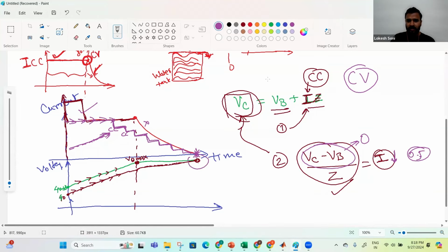Okay. So in that case, when you don't wait for zero and you stop charging, if I zoom this part, this final thing, this brown curve, which is of battery voltage, would sort of settle down like this. And this is that RC behavior which we discuss in our other webinars. So this is zoomed part. It would settle there only, more or less. Okay, so this is fundamentally what is happening in battery charging voltage and current wise.